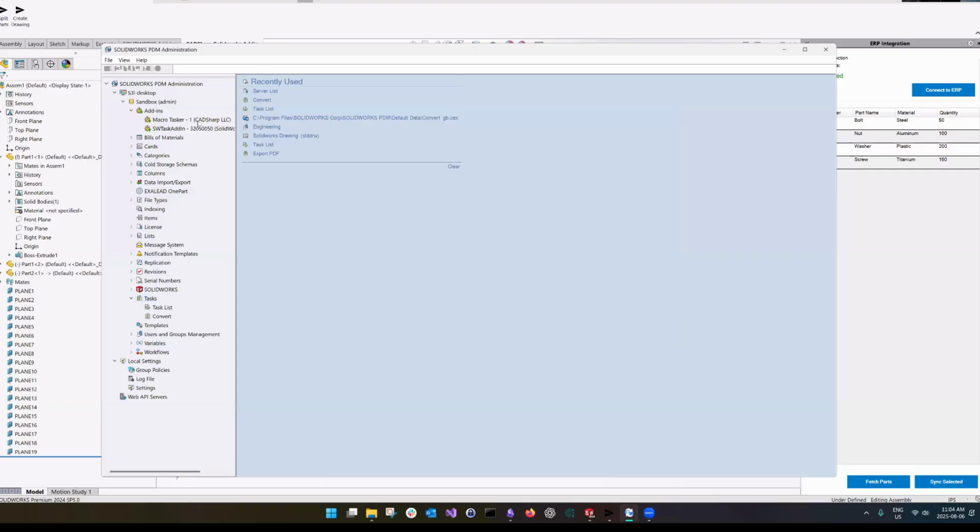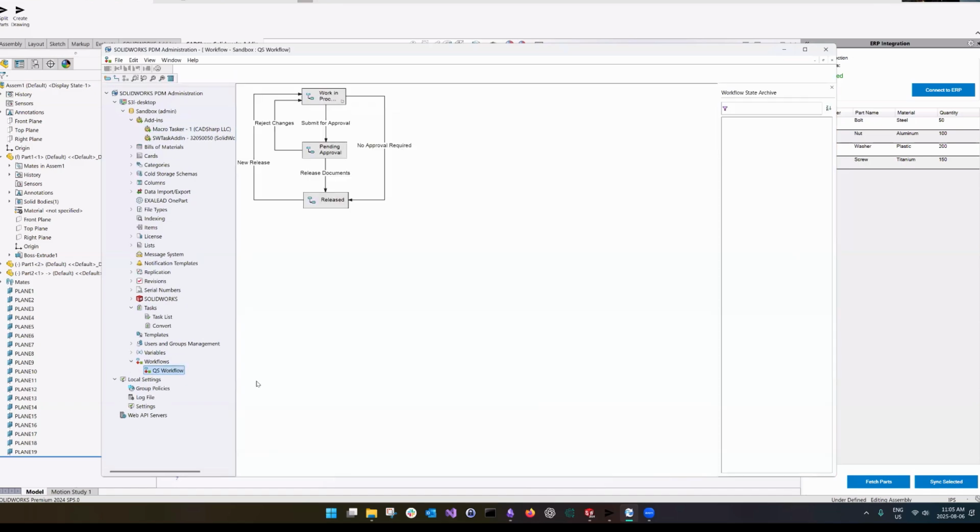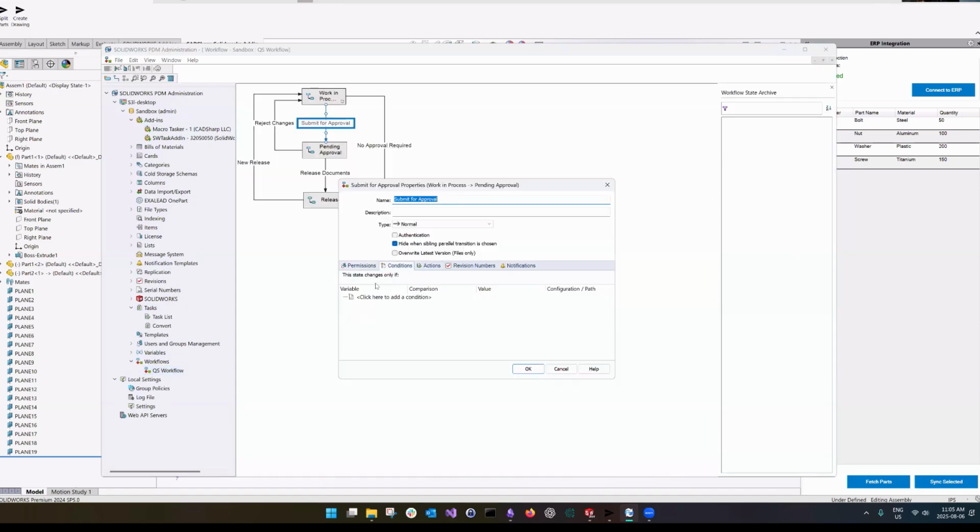One other thing we do a lot of with PDM add-ins is something called hooks. Hooks are events that happen in SolidWorks PDM. So for example, when a file gets checked in or when a file gets transitioned, we can intercept that event and add custom functionality. So some example use cases for that, let's say the functionality in PDM for a transition condition can't quite accommodate your workflow. So you can't quite get the business logic in here that you want to. We can then intercept that event, implement any business logic you want. It's literally limited to your imagination.